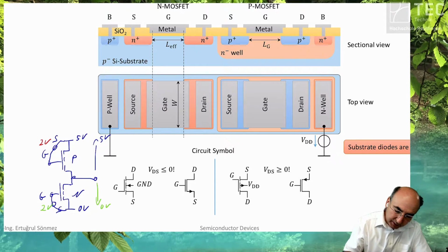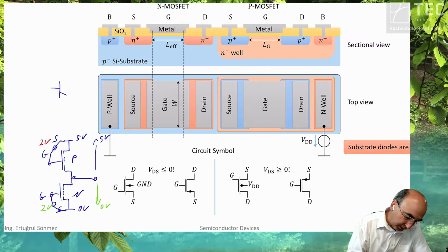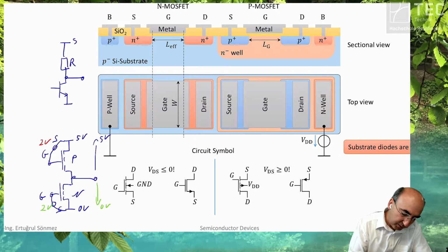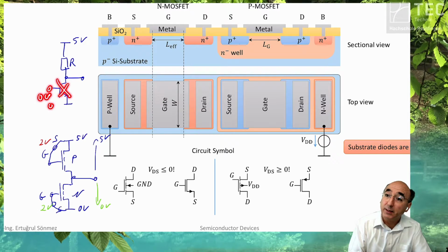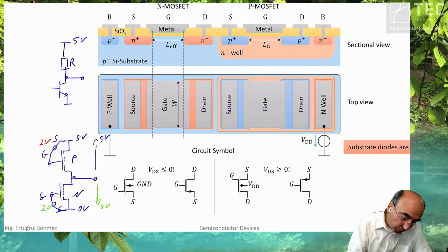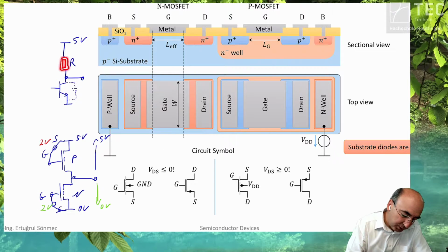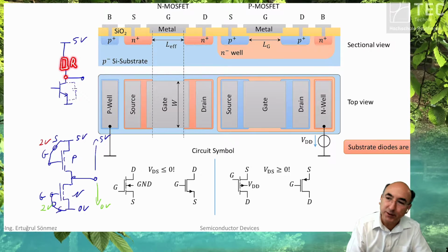Therefore, if you do a circuit in a bipolar transistor technology, the only device which switches this node towards the 5 volt is one transistor; if you do here 0 volt, then the transistor is switched off, and then all the parasitic capacitance of this node, this node has a parasitic capacitance to ground, all this capacitance needs to be discharged through this resistor.